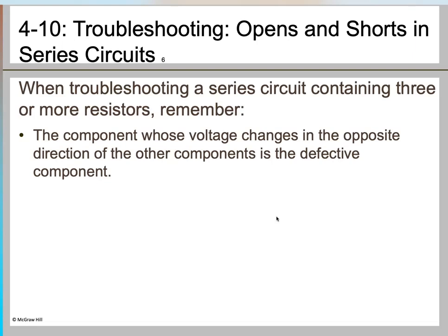In other words, in a series circuit containing an open condition, all the good components in the circuit will receive decreased voltage, equal to 0 volts. I'm saying it again: when there is an open in a series circuit, the voltage across all the rest of the elements will be 0 volts, there will be zero current, and all the voltage supplied by the supply will appear across the open terminal.